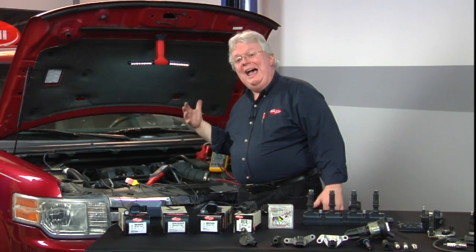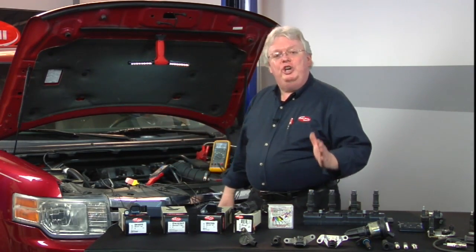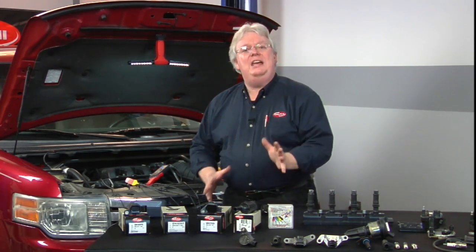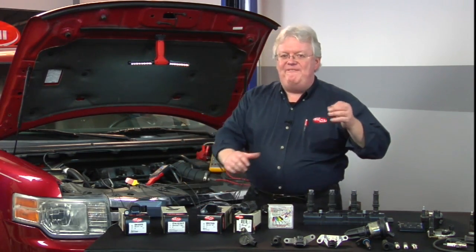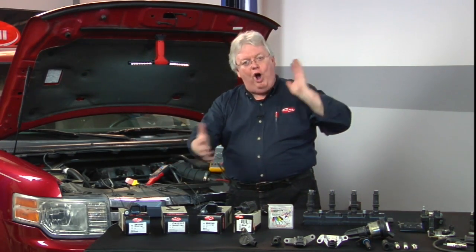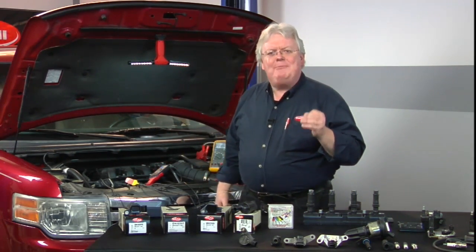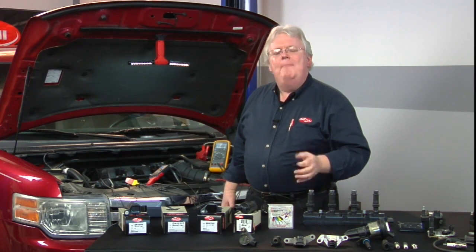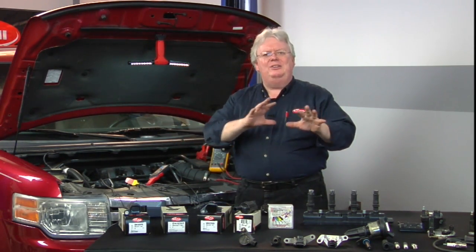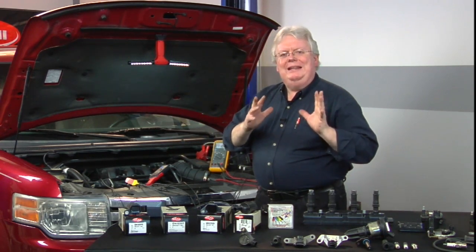This particular car has no problem right now. You want to measure good cars with your scope so that on those occasions, once a week, once a month, whatever, when you have the job that defies the flow charts, that defies moving coils and trying known good parts and all the things you do to try to save time in your diagnostics, you've got to dig down deep. You'll be proficient. So brush off that old scope, whatever you've got, built into a scan tool, get you a secondhand scope, whatever, and get scoping.